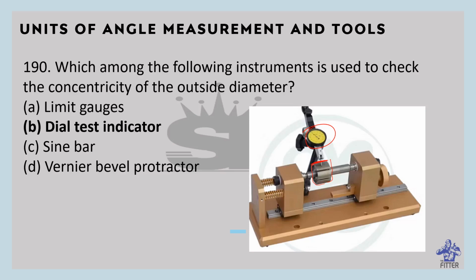The functions of dial test indicator are comparison in mass production, checking the center alignment, and determining errors in geometric shapes such as oval, round, and taper, and as a comparison of two heights or two distances between narrow boundaries.